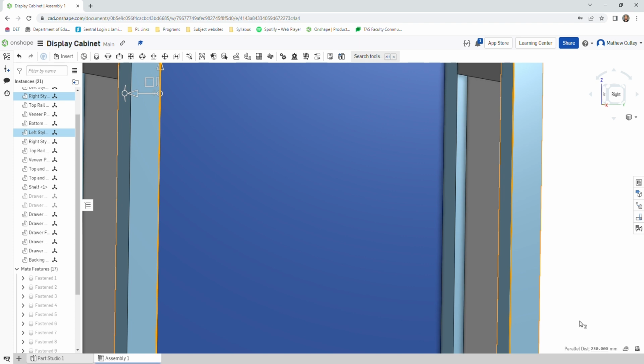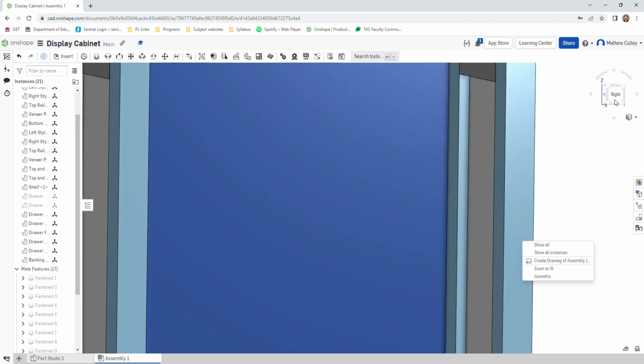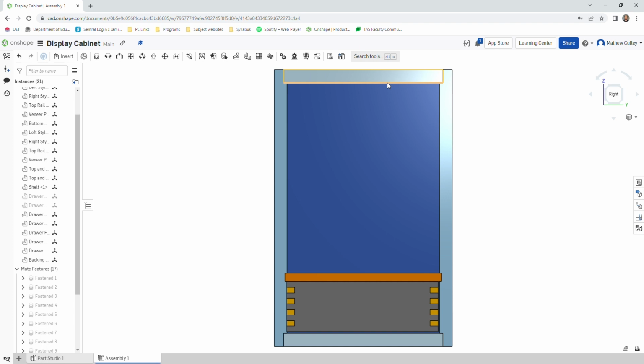Okay, we're going to give our door a little bit of room to move on either side, so we're going to give it a 2 millimeter gap either side. So then our door is going to end up being 226 millimeters wide. We'll do the same thing for working out our height. So clicking on this edge here and this edge here, 275 with 2 millimeters of play each side, it's going to end up being 271 high.